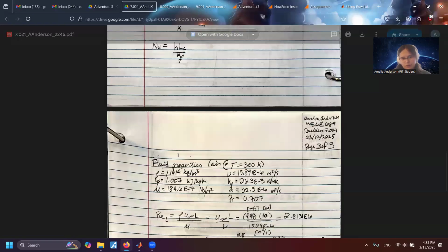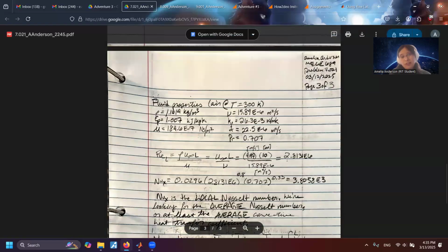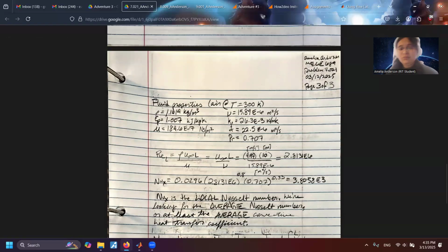So if we calculate our Reynolds number, that's pretty high. Reynolds number is a weird thing because the critical Reynolds number between turbulent and laminar flow happens at different points for different fluids in different situations, so there's not really a hard limit unless you're in pipes, and even then. So with this though, we can say that our Reynolds number is really high. So it's probably turbulent almost regardless of what you're doing.